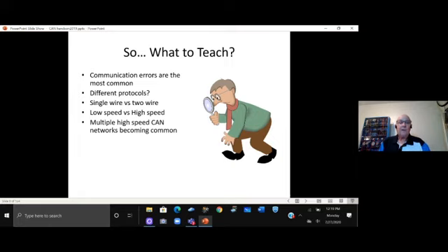Now, one of the things you're going to teach him is to look at the number of modules and look at the wiring diagram, and the two should be the same. Well, okay, that gets really hard to do. So you need to pick something simpler. What I always tell people is, when these people call up and say, hey, I'd love to donate a car, say, just a minute, and go to your other computer and look it up real quickly. If it's got fewer than 20 modules, take it, fix it, put it away in a corner, and use that to teach the basics. Okay? LIN is becoming more common, and again, I'll spend time with that.